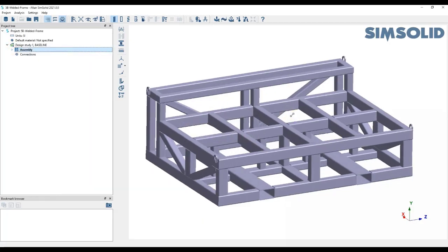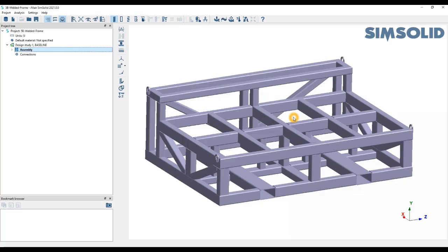Now the workflow we also recommend is that if you know you have an amalgamation of welded parts as well as bonded contacts or connections that you want to implement, we always recommend doing your welded contacts first. So within SimSolid you can create spot welds or seam welds or adhesives, just so you know that you do have lots of different virtual connectors that you can use.